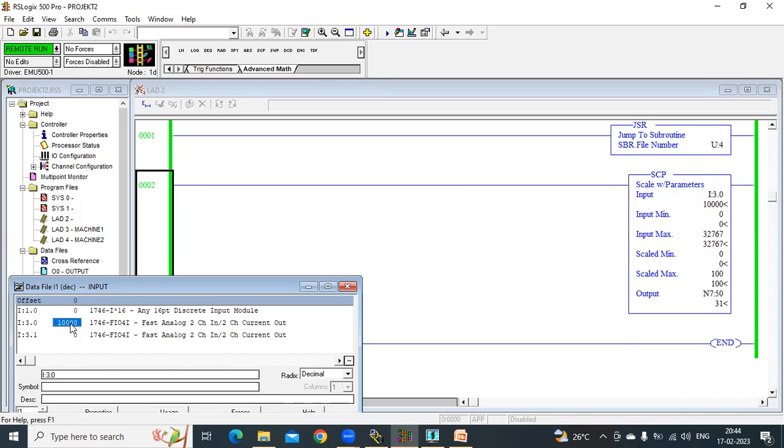So like this we are converting our data. What actual measurement we are doing at the field, the sensor ranging, like range minimum, scale minimum, maximum, we can select. It gives that output. But after conversion of the electrical signal to a digital count value, we get 0 to 32767. Okay, so now what else can we do here?